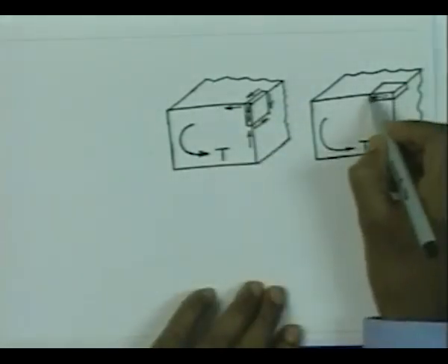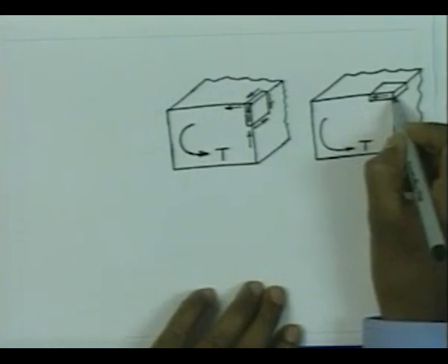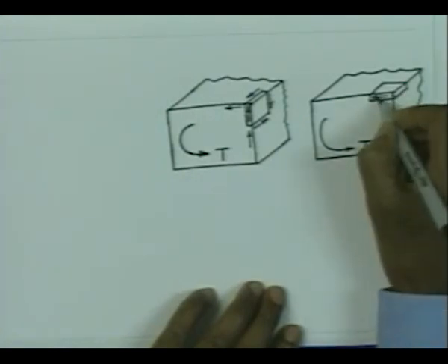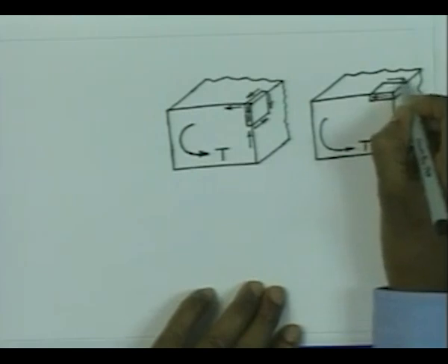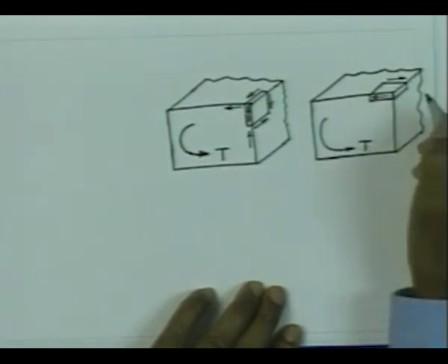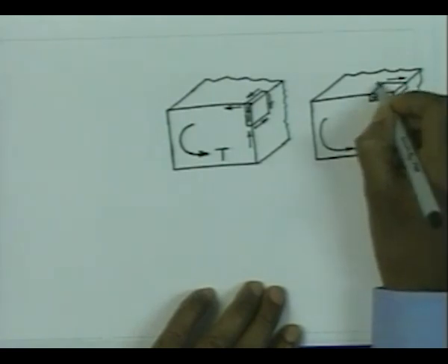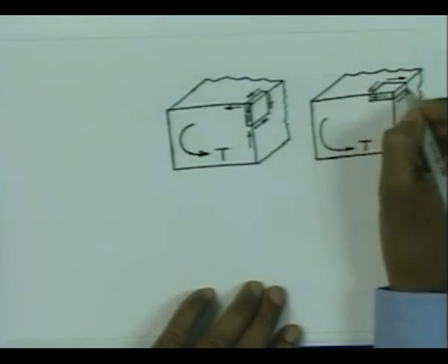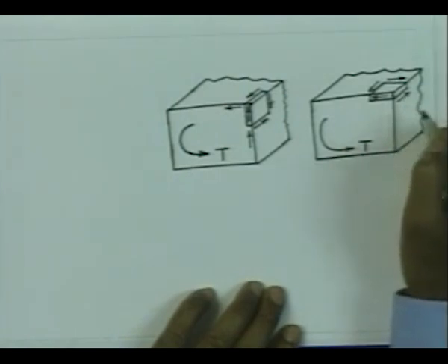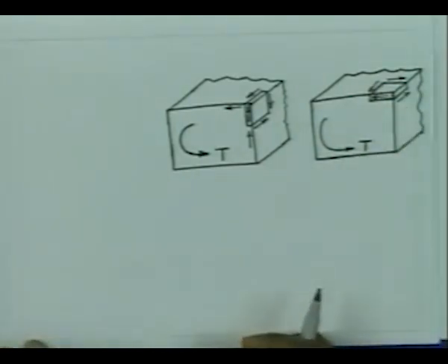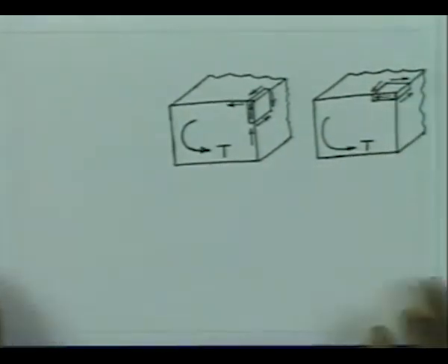By a similar type of argument, if non-zero stress is going to act at this point in this direction, then on the opposite face we will have stress acting like that, and the complementary shear stresses are going to act like this on this outer face. Since this outer face is again free of any external loading, this stress is 0, therefore this is 0, so also this and this is 0. So, therefore, you will find that these stresses are going to be 0.